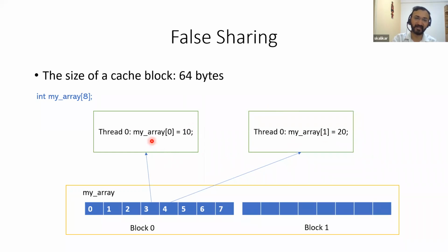But it is creating unnecessarily a lot of traffic to the NOC, the network channels, and that is going to degrade your performance. And eventually at the memory level, all writes of such things are happening in a sequential order. So this write is happening first at memory level. Then eventually when blocks are settled as a dirty ownership and all exclusiveness is shared, the other thread also writes to this.